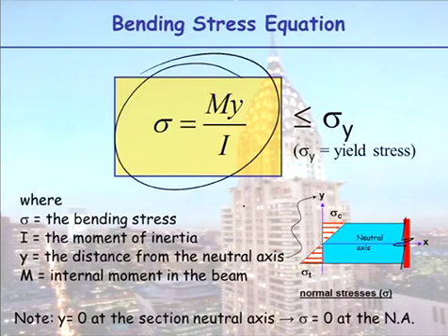This is the formula for bending stress. Now please don't be confused. I may ask you what the tensile stress is. You have to recognise it's bending stress we're talking about, and it's the tensile bending stress formula you need to use. If your beam is bending, if it's curving, it's the bending stress formula. Please don't take a bending moment diagram and your vertical reactions and somehow magically turn them into horizontal reactions and a compression force on your member. It takes a lot of imagination to do that.